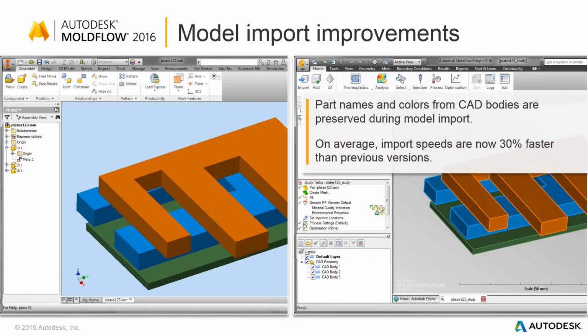This talks to that same thing, but also the fact that if you take a model from your CAD environment, in this particular case it's Inventor, but it works the same way with ProEngineer or SolidWorks, and there are certain colors applied to that model. If you import that model into Moldflow, if we have the information available, you would also take the exact colors across to the product.